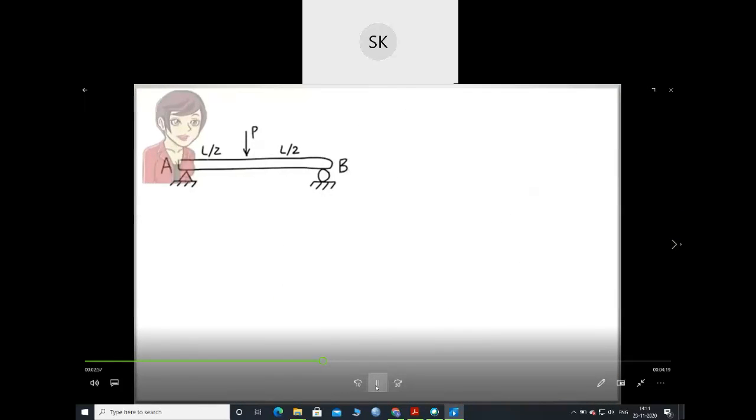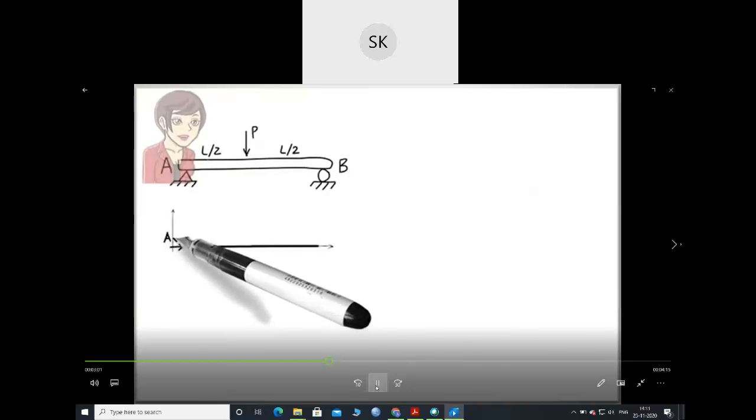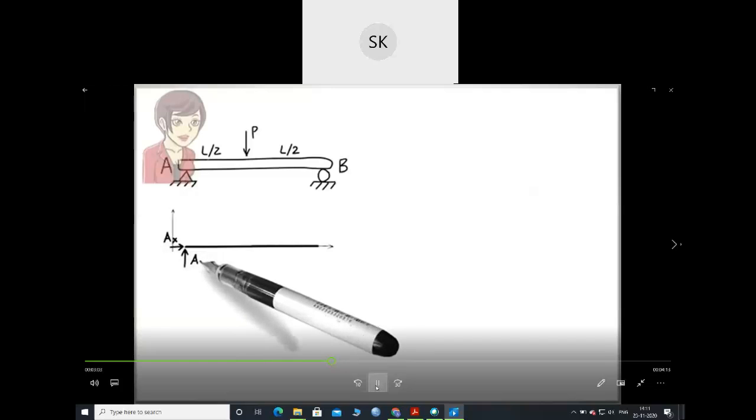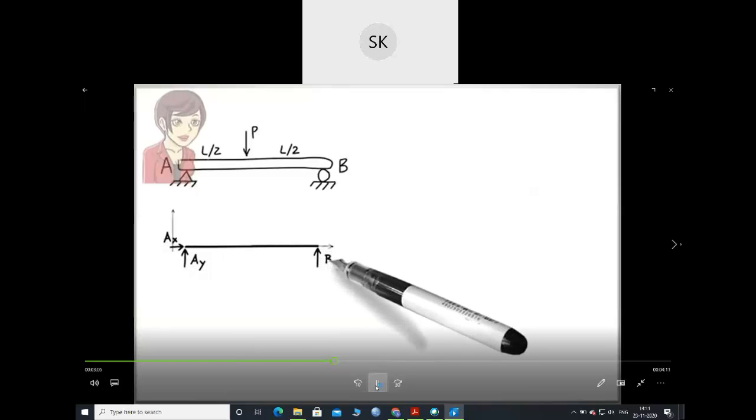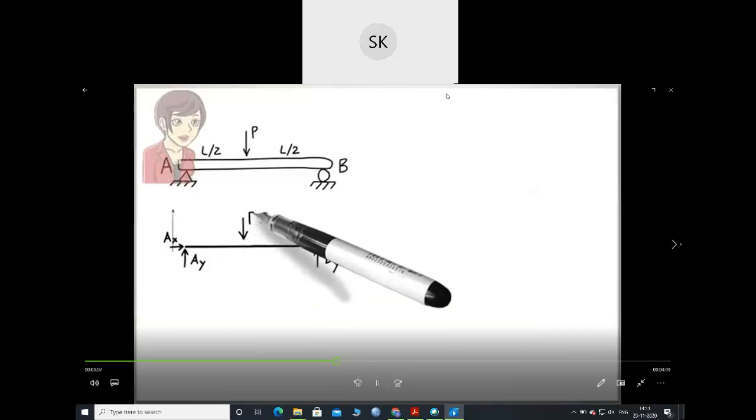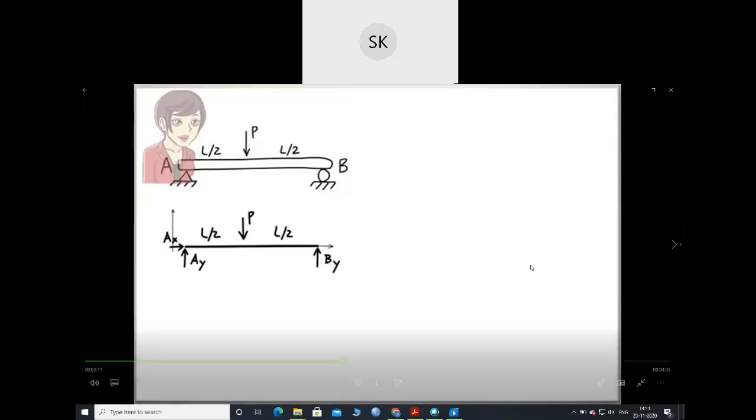In order to analyze a beam, it is customary to draw a diagram called the free body diagram, showing the applied and reaction forces and their locations in a Cartesian coordinate system. Note how each unknown force in the diagram has been uniquely labeled.